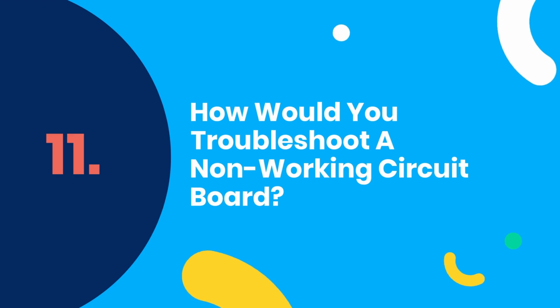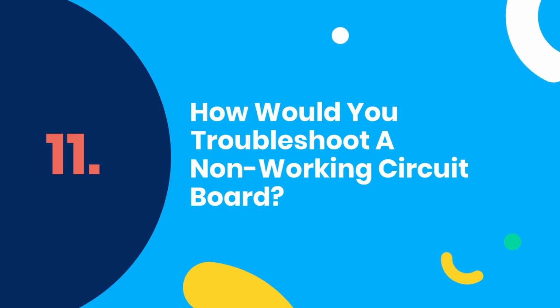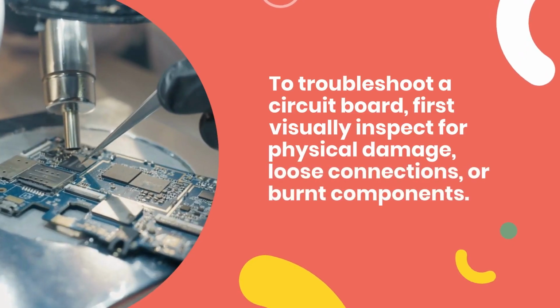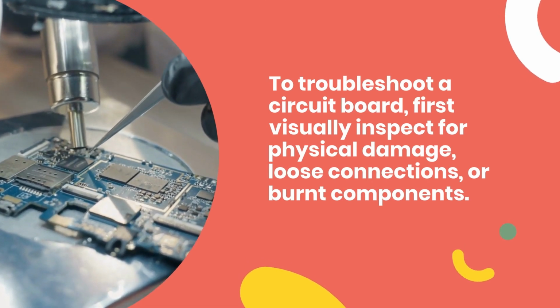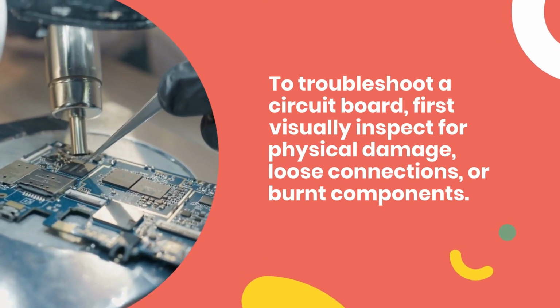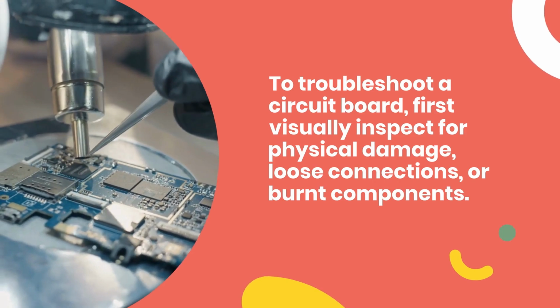11. How would you troubleshoot a non-working circuit board? To troubleshoot a circuit board, first visually inspect for physical damage, loose connections, or burnt components.